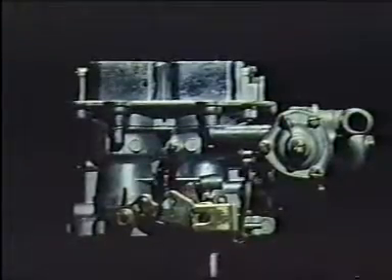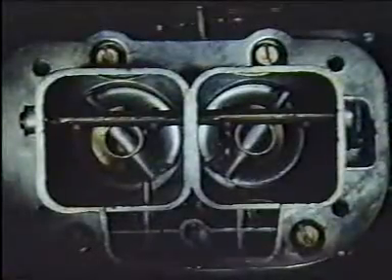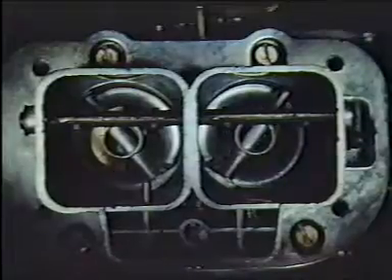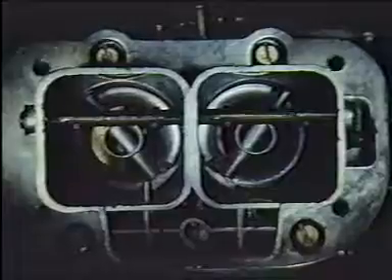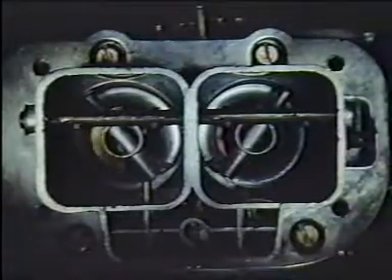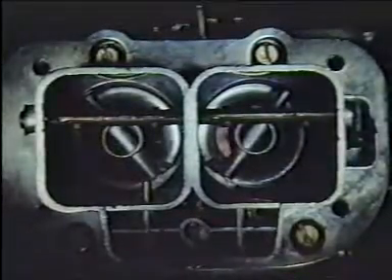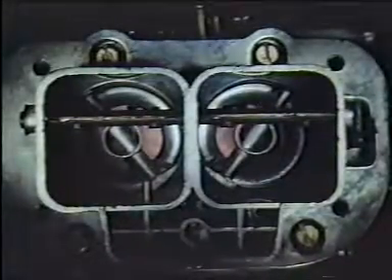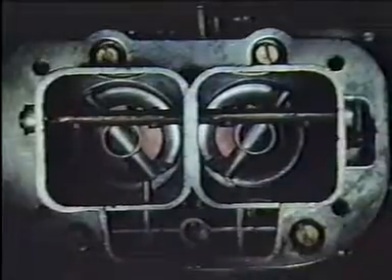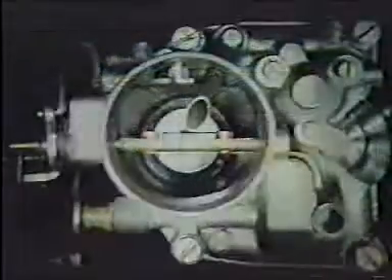It consists of two carburetors of different diameters side by side in the same casting. At lower revolutions, the needs of the engine are met by the smaller carburetor. At higher revolutions, the larger diameter carburetor comes into operation, greatly increasing the flow of mixture into the engine and improving its performance. The task is always the same.